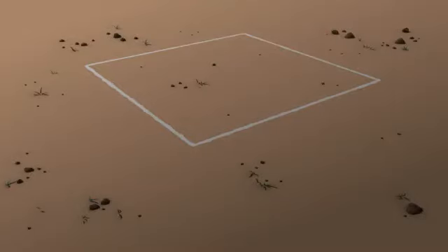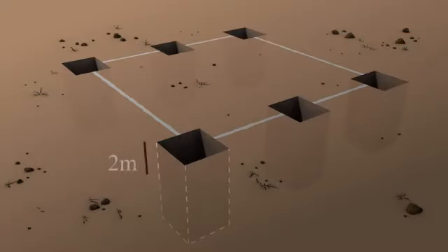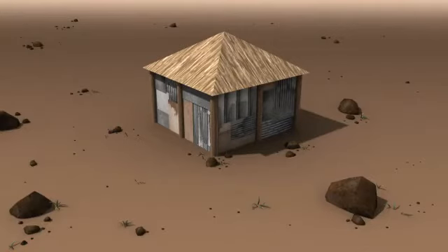Before building a shelter's foundation, it is important to understand the type of soil over which the shelter will be built. Digging the soil along the location of the future foundation will allow one to know the type of soil. You can dig the holes in 4 to 5 different places. Holes should be at least 2 meters deep to allow a proper assessment of the soil type. The type of soil is important for the stability of the shelter.